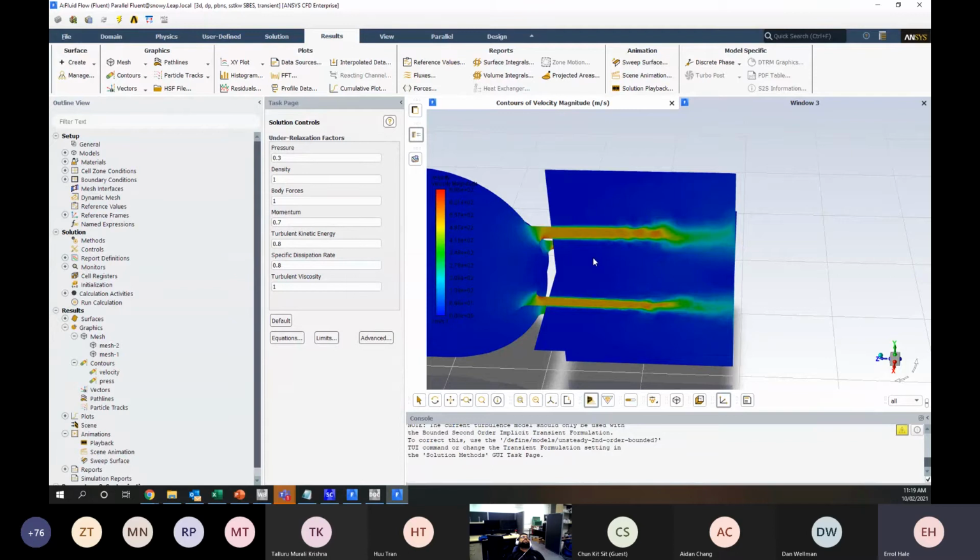How do you handle a varying transient solution when you're doing a mesh independent study? Great question. Difficult one to answer. I'd be looking at trying to get a steady state case that could be assessed for convergence before turning on transients, rather than using a transient simulation for doing a mesh independent study, if that's possible.